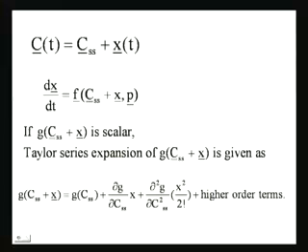Fine. So here we are concerned. So what is our concern? Our concern is small values of x. Why is that? Because, A, it's a linear stability analysis we are doing. B, we are trying to figure out how the system behaves in the vicinity of the steady state. So if you are trying to figure out how the system behaves in the vicinity of the steady state, what is the deviation from the steady state? x.